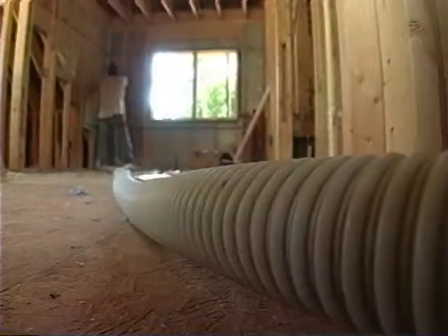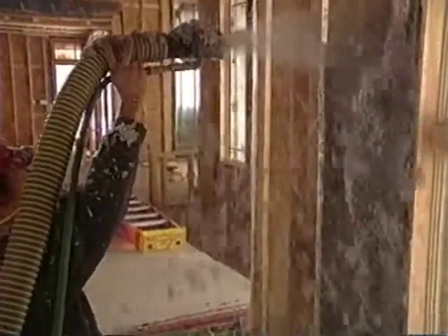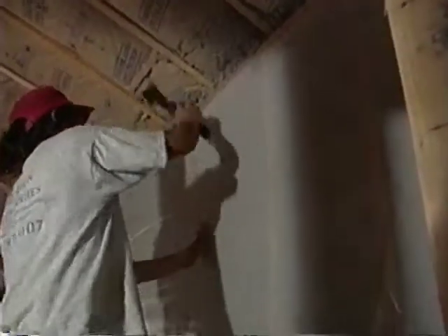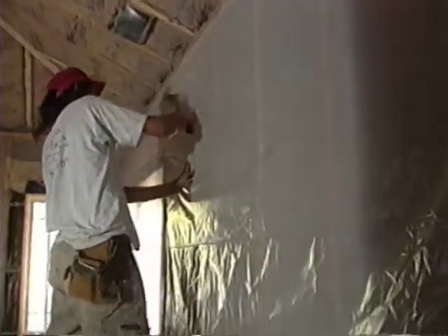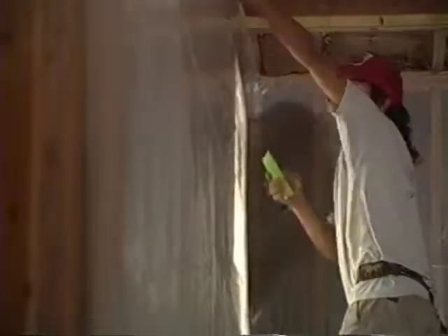Many different materials can act as vapor barriers. When installing dense packed cellulose, the nylon reinforced polyethylene that holds the cellulose in the wall cavity can act as a vapor barrier. When installing sprayed cellulose or unfaced fiberglass batts, stapling sheets of sealed polyethylene tightly over the stud assembly provides a vapor barrier. Coated kraft face paper on batt insulation can be an effective vapor barrier. Any material that does not allow moisture to pass through it can act as a vapor barrier.